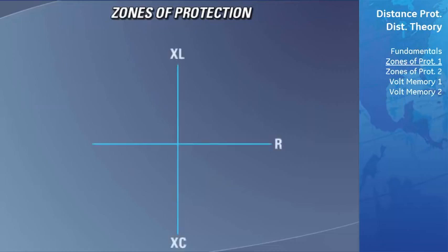To program distance relays, you need to configure the impedance of the line, where any impedance less than this value will indicate a faulted line. This is done in modern distance relays by creating zones of operation on the RX diagram. If the impedance calculated at the point of measurement of the power system ever falls within this zone, the relay will trip.